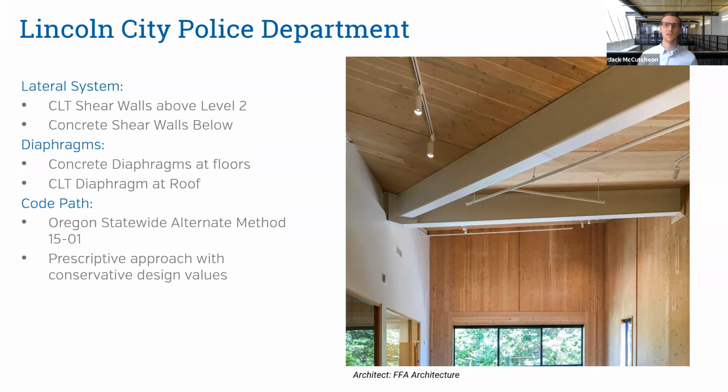Now, it's important to note that while that's a prescriptive approach, it is rather conservative in how we need to calculate our forces. So one area where the code, I think, is going to catch up in the next couple of years or so is identifying CLT as a more widely used material in lateral systems, and it's not going to be as conservative. Reid will touch on that a little bit later on.